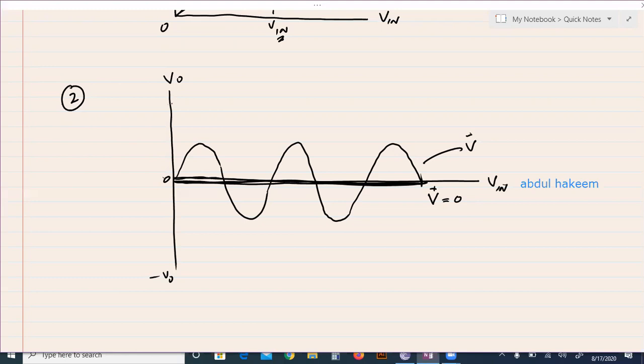First of all, we will mark supply voltage positive and supply voltage negative on both sides. And then we will draw vertical bars where both inputs are equal. So these are the points where two inputs are equal. A vertical bar at this point, and the height of the bar must be equal to the value of the supply.